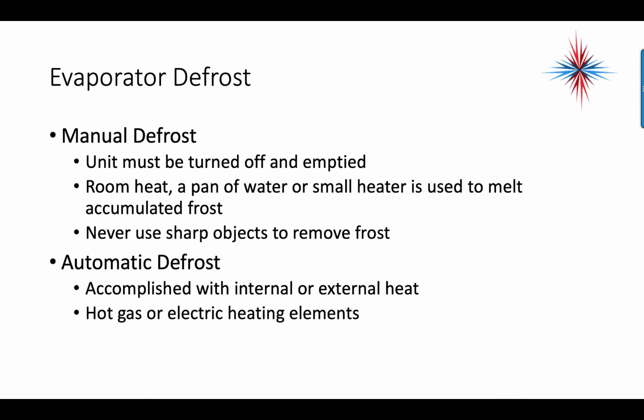So there's two ways for evaporators to defrost. One is manual defrost. The unit must be turned off and emptied. Room heat, a pan of water, or a small heater is used to melt the accumulated frost. You'd never want to use sharp objects in a freezer to remove frost from an evaporator. Just not a good idea.